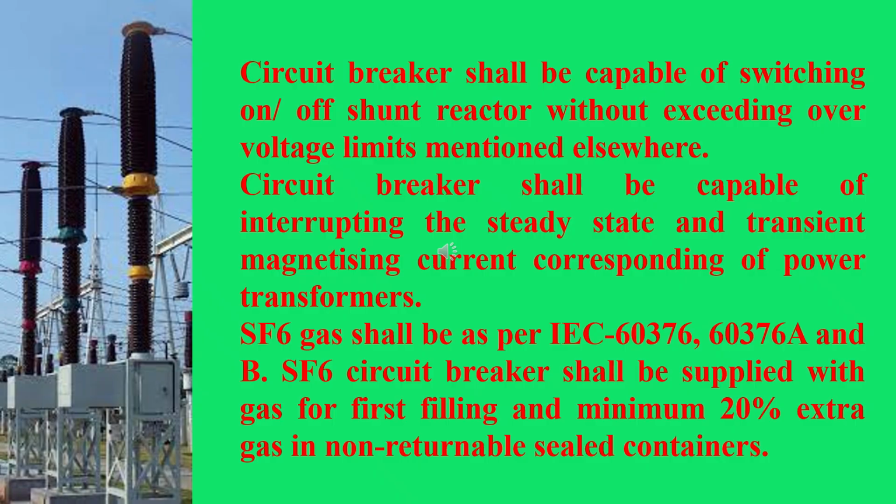Circuit breakers shall be capable of switching on and off shunt reactor without exceeding over voltage limits mentioned elsewhere. Circuit breaker shall be capable of interrupting the steady state and transient magnetizing current corresponding to power transformers.